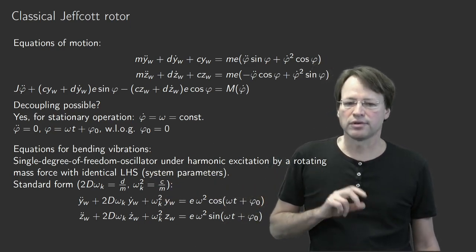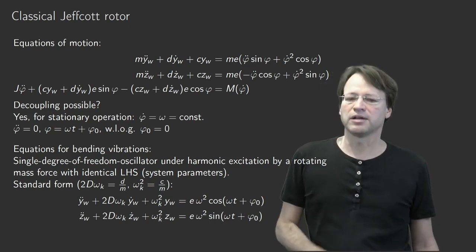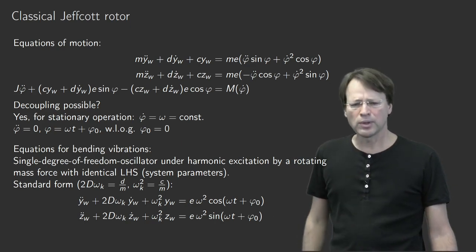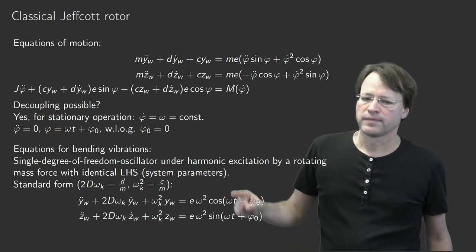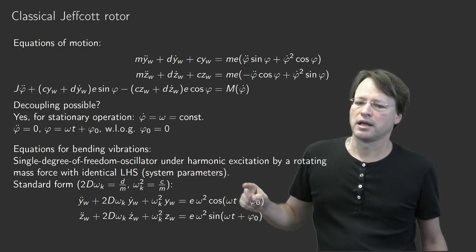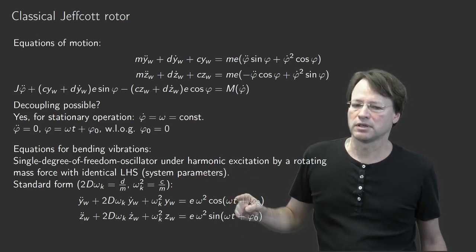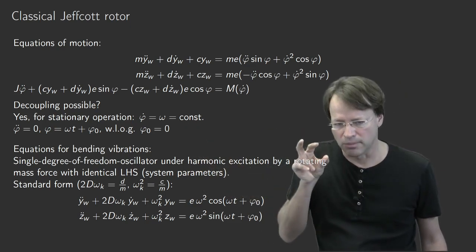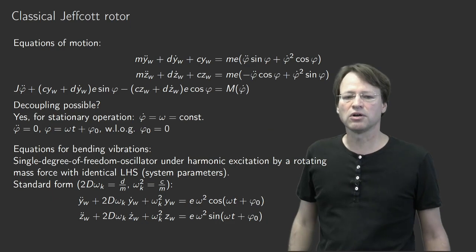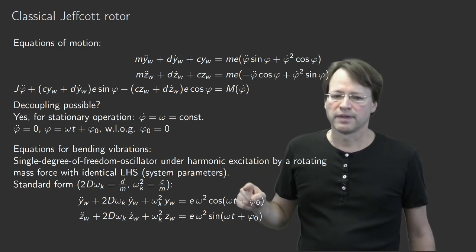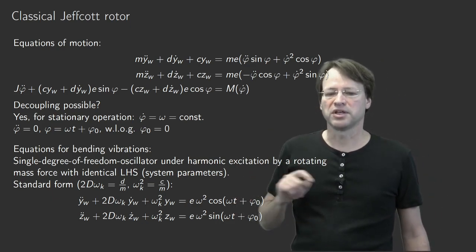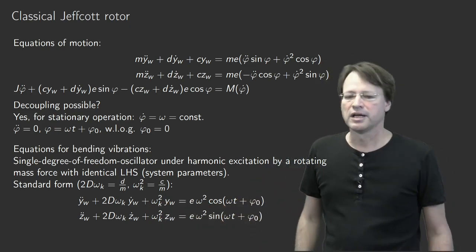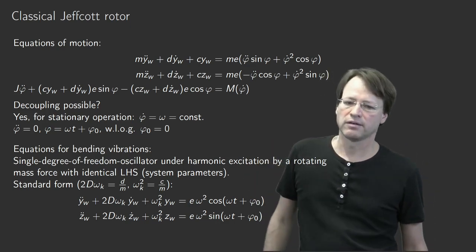The k refers, and this is the general language here in that chapter, to the term critical. What is critical there? Well, there's another omega in that equation without a k. It's that omega from stationary operation. It's that omega that comes from the rotational velocity of the rotor. Now assume you will have omega equal to omega k. What will happen? Well, you will be in or close to resonance. And this is called the critical velocity.